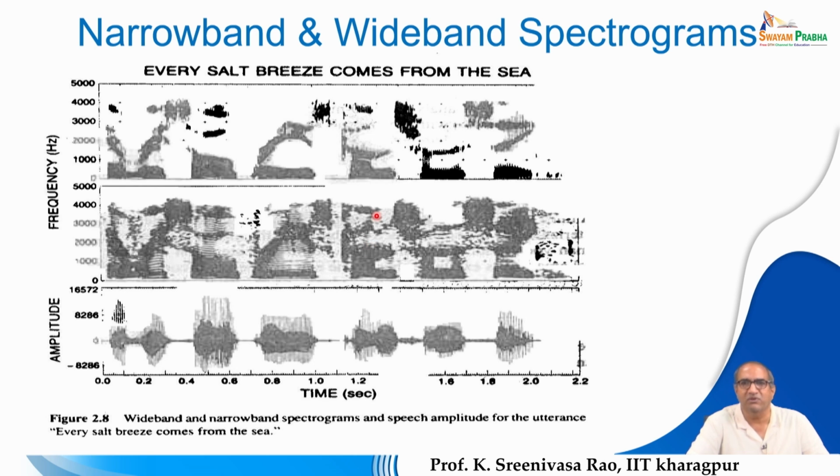This is because of the resonances offered by the vocal tract. When you utter a sound, depending upon the shape of the vocal tract, in the frequency range of 0 to 5 kilohertz, around 95% of the energy will be distributed in only 3 narrow frequency ranges.